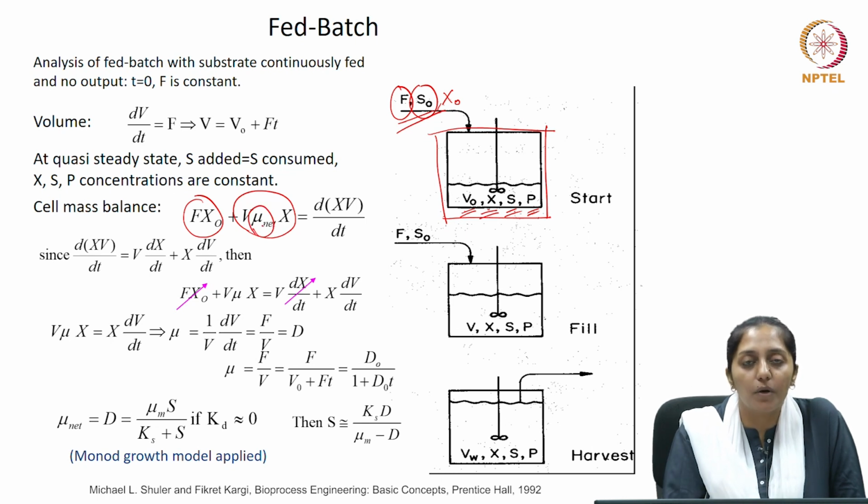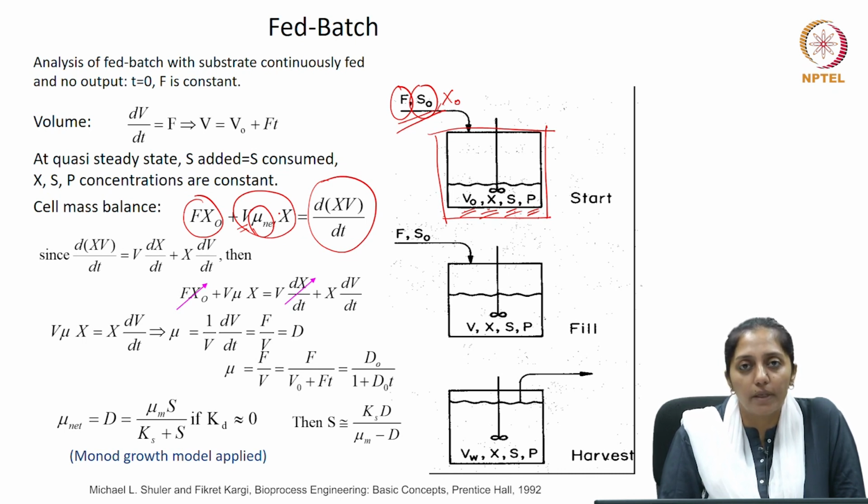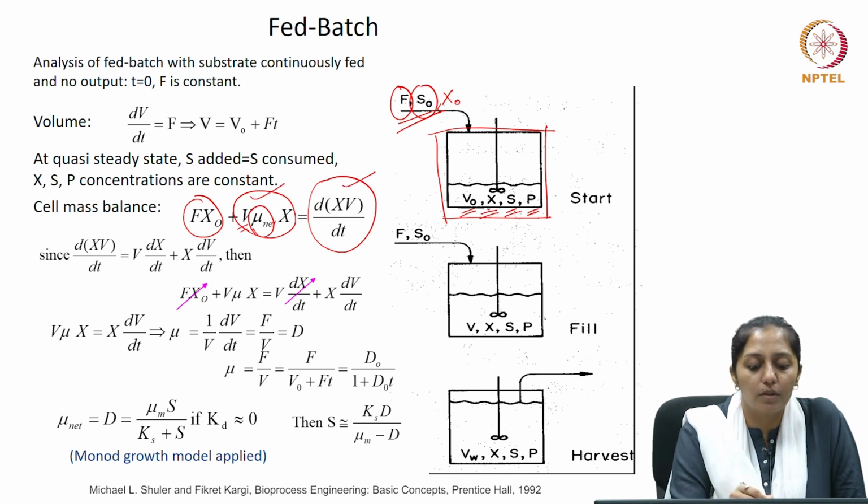So it is talking about the rate at which the biomass is growing inside the reactor with a volume V at a time, and this is equal to the rate of accumulation inside the reactor. Now the outlet term is 0, there is no consumption, so consumption term is also 0. So therefore we only have accumulation, growth and inlet in the continuity equation.